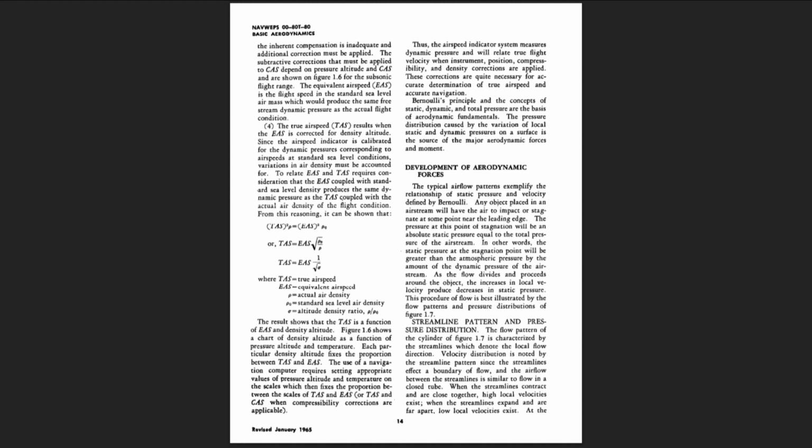Bernoulli's principle and the concepts of static, dynamic, and total pressure are the basis of aerodynamic fundamentals. The pressure distribution caused by the variation of local static and dynamic pressures on a surface is the source of the major aerodynamic forces and moment. Development of aerodynamic forces: the typical airflow patterns exemplify the relationship of static pressure and velocity defined by Bernoulli.